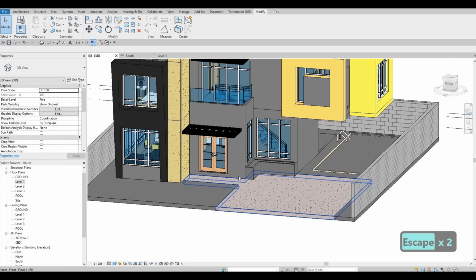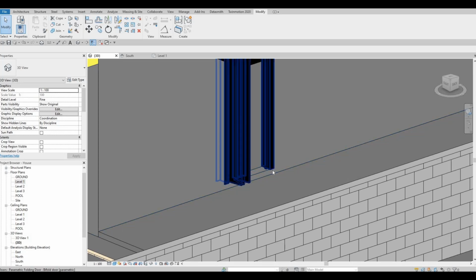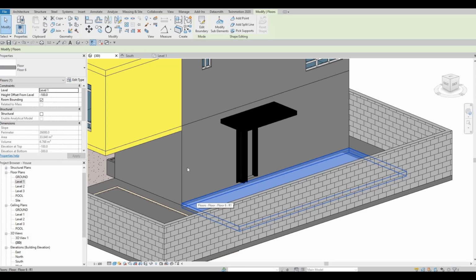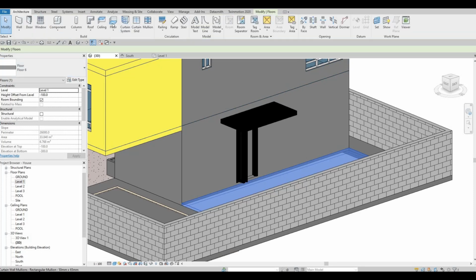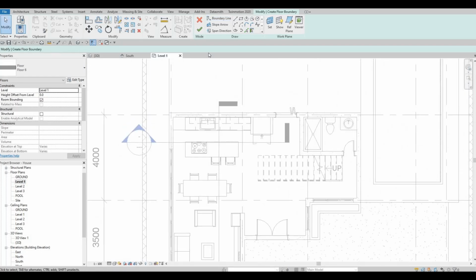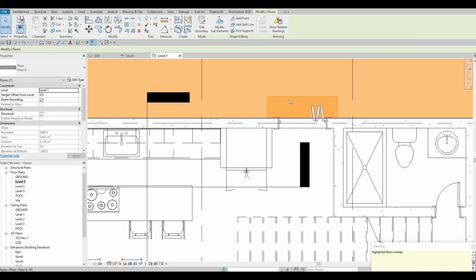And then now, because we have that, here we need to add 100. So this is a floor that we created. I'm just going to use this. This is just going to be a simple, just one step stairs. So I'm just going to add another one. So click on floor and then go to level 1, and then here we just need to add a floor like that. Very simple.